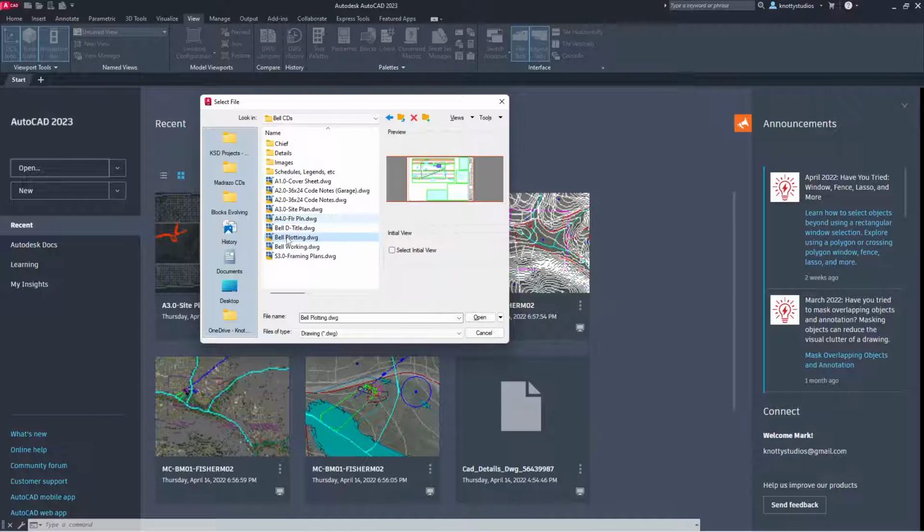And then plotting is a big, huge file that is an XREF of everything. So I can see what you're doing without disturbing you, because if I get into the same file you're in, that could cause havoc. But the plotting file is just a reference to every drawing, and it is where I plot the final sheets from. So I can actually open them up, take a look at them, send you notes, tell you what's going on.